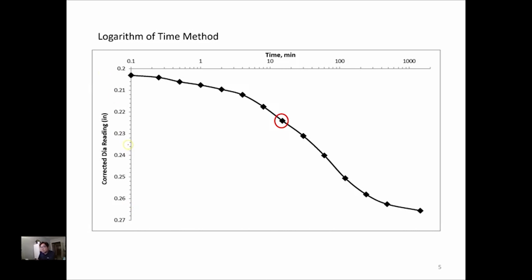So half of it is here. Pretty much you go to your y-axis and look at the midpoint, and also the midpoint of the first region, right there. So this point represents roughly 1/4 of the total settlement.